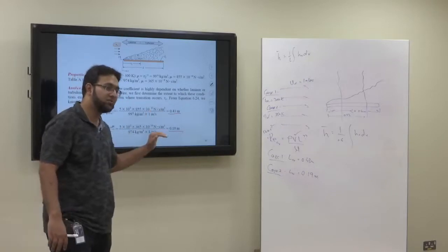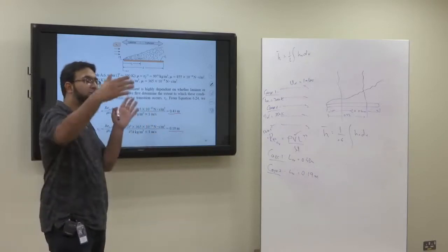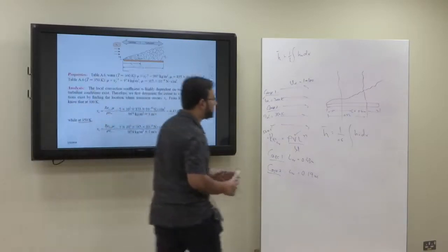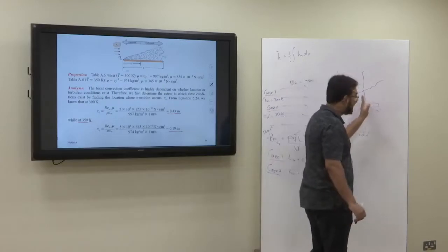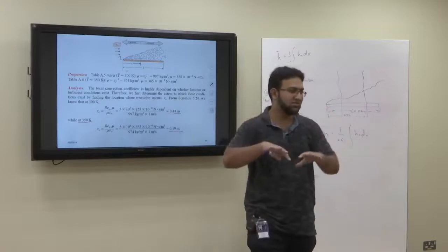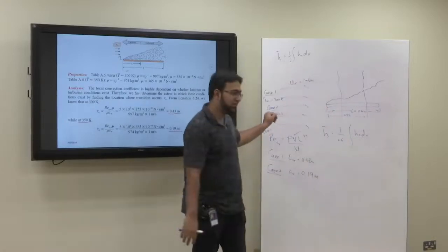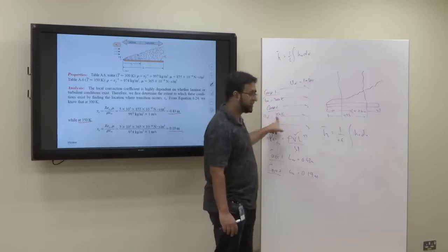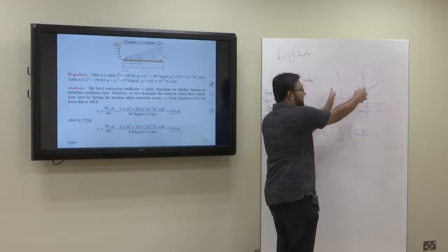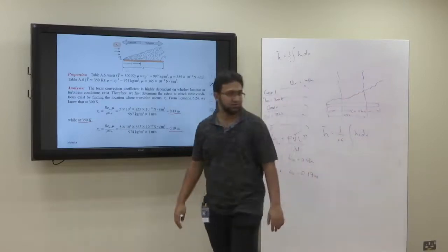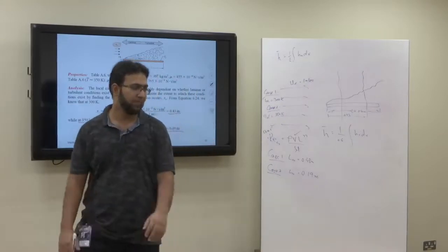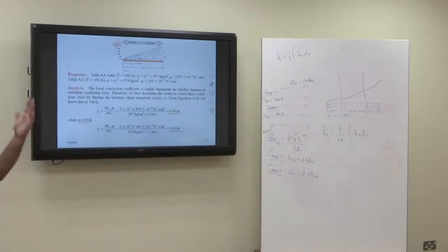There are 2 separate cases. For the first case, it is 0.43. That means for 0.43 meter it was laminar; from 0 to 0.43 it was laminar, then becomes turbulent. Case 1 complete. Case 2 is a separate case. Now again water is flowing, but this time water is at 350 Kelvin. So in case 2, for 0.19 meter it remains laminar, after that it is turbulent. Is it clear? Don't mix them up. It's like solving the problem 2 times.